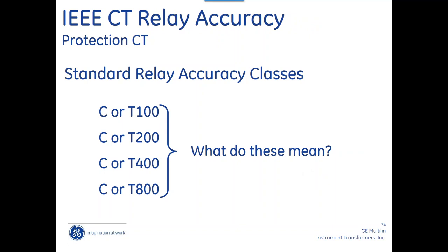So you should size CTs based on the anticipated load you will see. It's one of the questions Spencer asked me. It depends on the application, and I'll get into that more. Spencer, you're mainly dealing with protection CTs, and we get into a thing called saturation, and from that, I'd rather have a higher ratio, so I eliminate saturation.